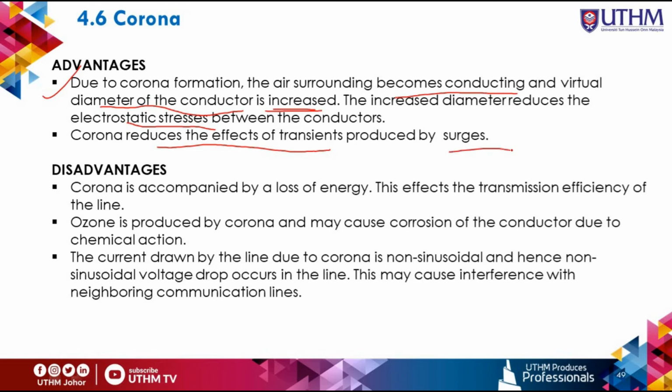However, the disadvantages of corona. Corona is accompanied by a loss of energy, which will affect the transmission efficiency of the line. Ozone is produced by corona and may cause corrosion of the conductor due to chemical action.